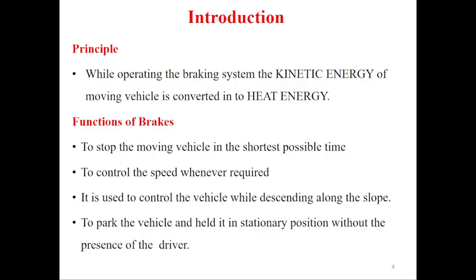The principle of the braking system is that while operating the brakes, the kinetic energy of the moving vehicle is converted into heat energy. There are different functions. The first function is to stop the moving vehicle in the shortest possible time. The second is to control the speed whenever required. The third is to control the vehicle while descending along a slope. The fourth is to park the vehicle and hold it stationary without the presence of the driver.